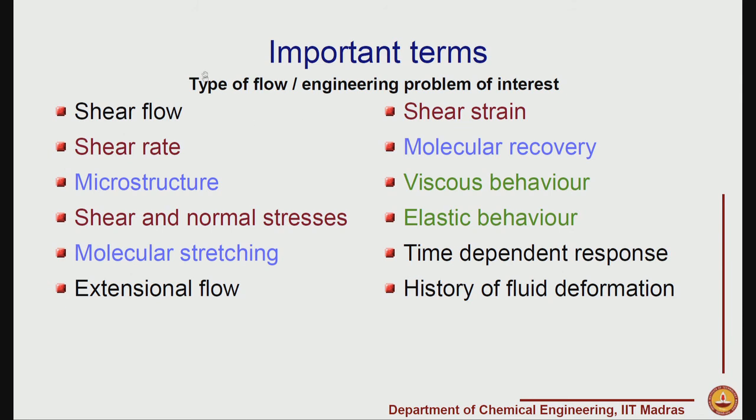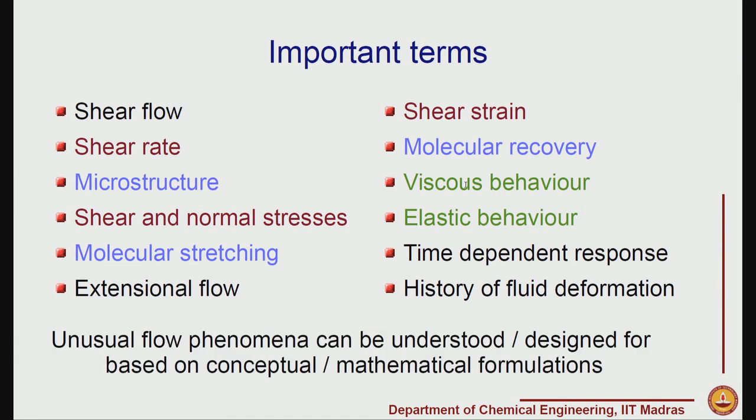And finally, we have of course the type of flow, or whatever the engineering problem of interest is, which decides what types of flows are important: whether shear flow is important, whether extensional flow is important, whether we need to look at time dependent response, and whether we need to look at the history of deformation that was imposed in addition to the current deformation the fluid is undergoing. All these put together are important if we have to understand unusual flow phenomena such as rod climbing or secondary flows in non-Newtonian fluids.